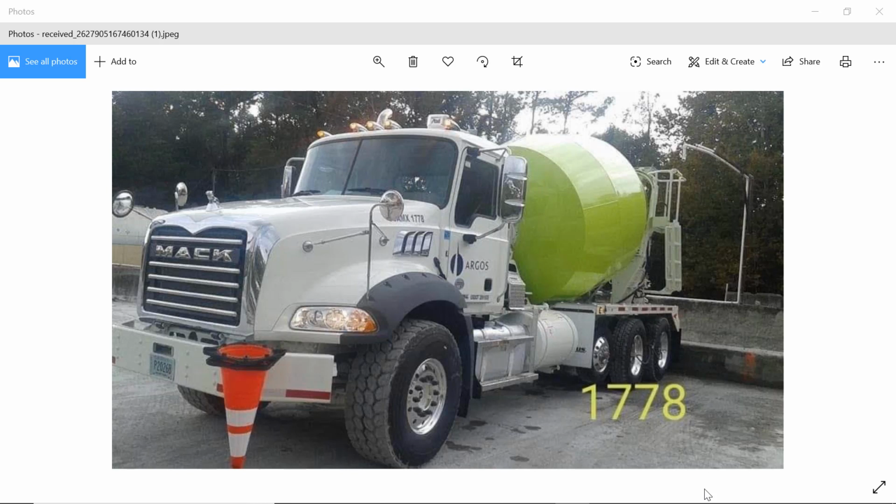Fine aggregate free moisture is equal to 2.9%, which is equal to 2.9 divided by 100 plus 1, which is equal to 1.029. Adjustment due to extra water in the fine aggregate is equal to 1,366 times 1.029, which is equal to 1,405.6140, which is equal to 1,405.6140 minus 1,366, which is equal to 39.6140 pounds free moisture.